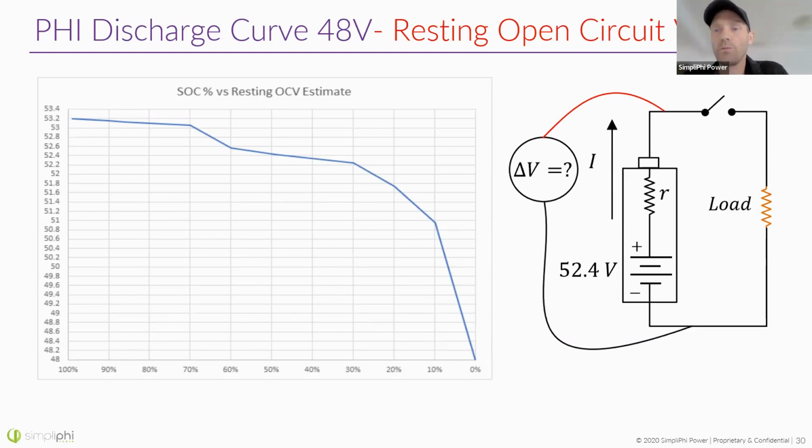It depends. Typically beyond about 4 years, unless you have a really large battery bank that is not heavily taxed, meaning that you're not using the battery at a high C rate, we don't recommend adding batteries beyond about 4 years. So contact our engineers and they can give you a recommendation on how to add more units. If your batteries are just a few years old, then no big deal adding batteries to the bank.